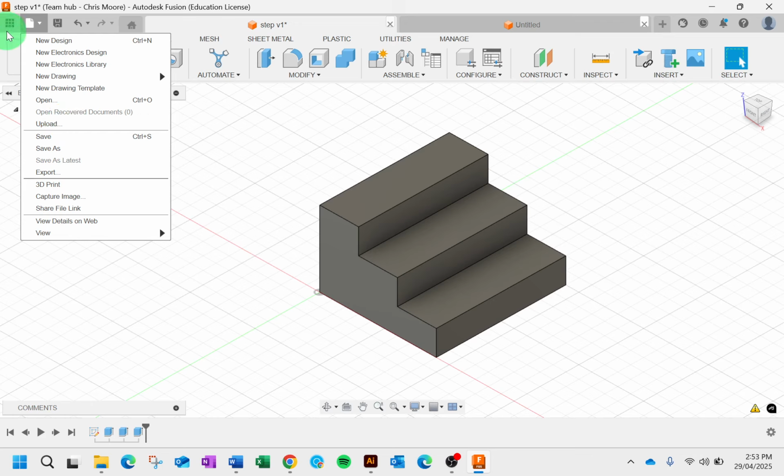Beside that, the main one we're going to look at is the display settings. Under display settings, we've got the visual styles, and you might be changing it to wireframe or to with hidden edges. However, for more complex designs, you'd be using hidden edges. However, the default shaded with visible edges only is really suitable. For the grids and snaps, you can turn off your layout grid, and you can also snap to grid and change the grid settings. They'll be in millimeters.